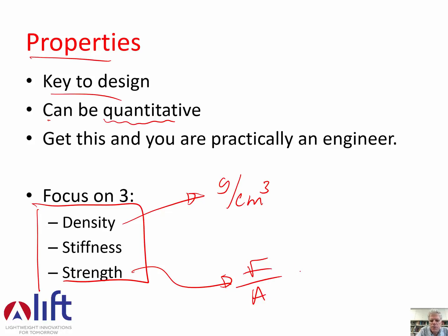And if you put that in SI units, that's usually newtons per square meter. And Newton per square meter we often call a Pascal. Newton is a fairly small force. Remember, that's the force that a medieval apple might have on the earth from Newton's days. Square meter is a big thing. So 1 Pascal is a really, really small stress or pressure, so we often deal with millions of pascals, or MPa, megapascals.